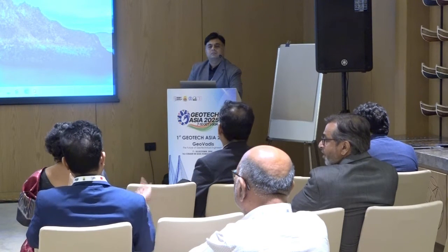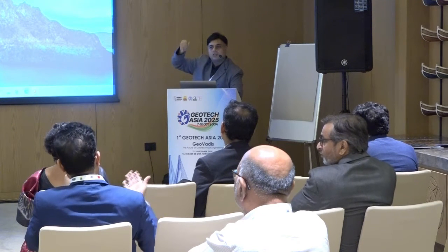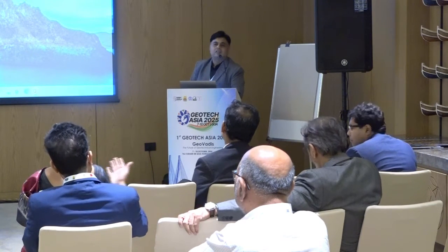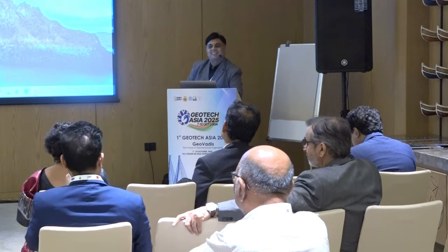And another problem in a congested city like Chennai or Mumbai is that you don't even get a space to put markers on the surface. So you will have to come up with a solution for how to put a 2 meter deep marker under those hutment areas where there's no space. But it is only a rod, sir, which goes down, right? I'm saying only a steel rod. For putting a rod also, you need some open surface. In Mumbai hutment areas, there's no open surface, because along the tunnel alignment you have to cover 5 meters or 10 meters on both sides. Yeah, you're right. There you won't get space. So sir, just do some research in that field and find out how that problem can be resolved.